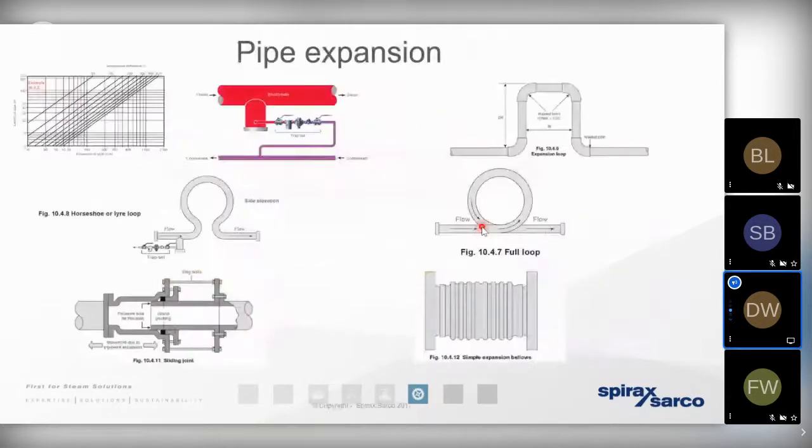And similarly, we don't manufacture pipework expansion, but we know that it's vitally important that you consider the effect of expansion. Again, steam distributed at a high pressure, high temperature in a steel pipe over a considerable distance, it means that the network will be exposed to a little bit of expansion. So we can give guidance with regards to how much expansion can be expected.